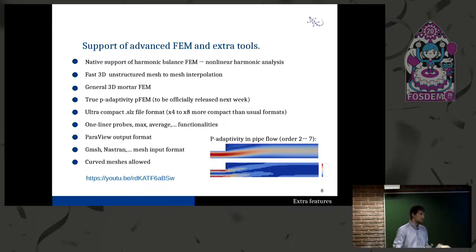You can easily reload it later, even if you have no idea of how the simulation was done. You have one-liner probes, so if you want to know the value in one specific position, you have the interpolate function. You have maxes, averages, integrals, whatever. This is very straightforward to use.